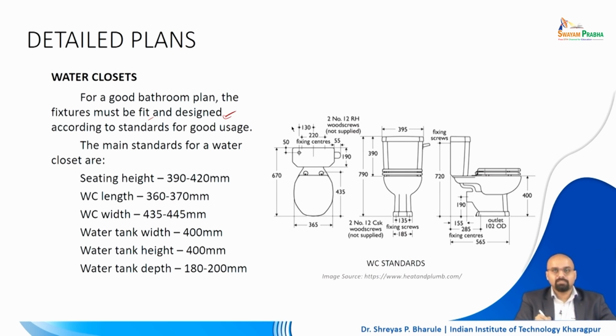So these are some of the things which are to be taken care of. Often what happens is, just before we actually go and buy certain appliances, say for example you are doing a commercial office wherein a lot of people will be coming to work, you will require large size toilets where you will have 4 or 5 WC units, about 5 to 7 wash basin units, and maybe in the ladies toilet you will have 8 or 10 water closet units, and on the wash basin side 8 or 10 wash basins, and all of that is to be